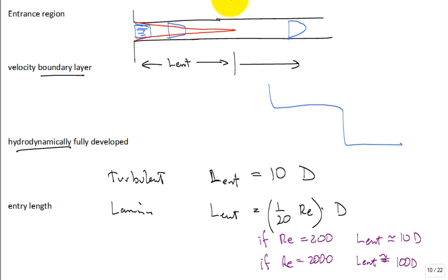And so what they'll do is they'll say, if you're coming around a bend, or if you've recently added fluid into the pipe, you have a union and two pipes coming together and a third pipe going out, you need to put that flow meter about 10 diameters downstream of the last disruption that would make it kind of restart hydrodynamically, so that it becomes fully developed.